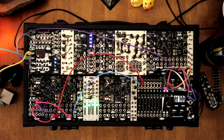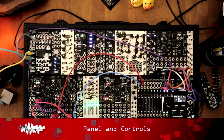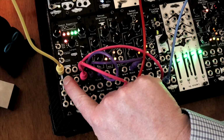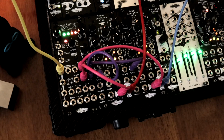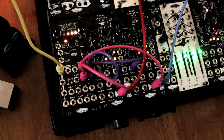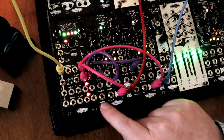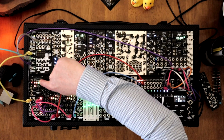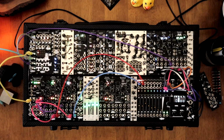Let's take a look at the panel and go over the controls. We'll start by adding a trigger signal. There are 4 trigger inputs on the left, and they are normal top to bottom, allowing the trigger to advance all the others below it if no others are patched. Triggers are passed through to the 4 trig outs, and the 1 volt per octave voltages generated by the module are sent to the 4 CV outs. The 4 LEDs at the top show the voltage changing on each of the 4 channels.